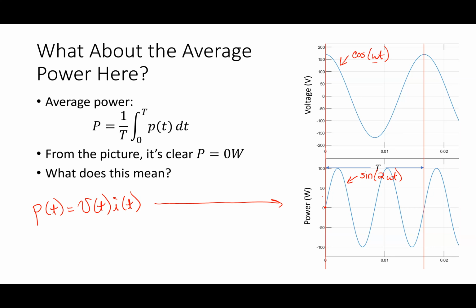There's a shift also vertically, right? So what's the average value as I go through one period of that waveform on the bottom? 0. So this is the weird thought. Now I have an inductor, I have an impedance here. So when this guy is positive, what's happening during the positive part? Absorbing. So here is absorbing power,